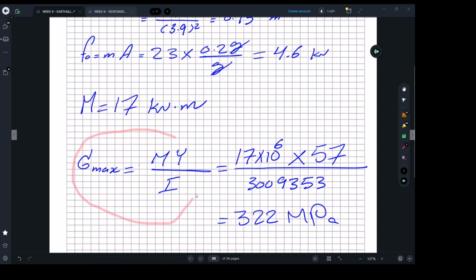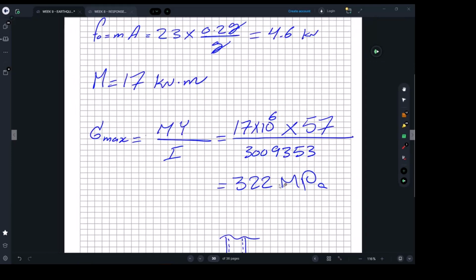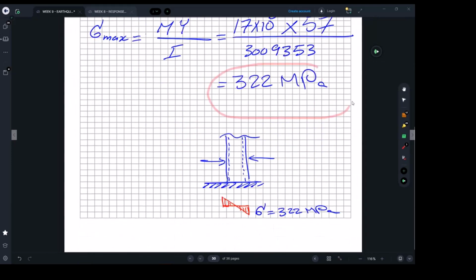Then you just work out your stresses, which I think you have all mastered because you know what this formula is doing and where it's coming from. So you end up finding your stress at the bottom of the post. And that's it. So again, this shows you a practical application for the spectra or spectrum curves.